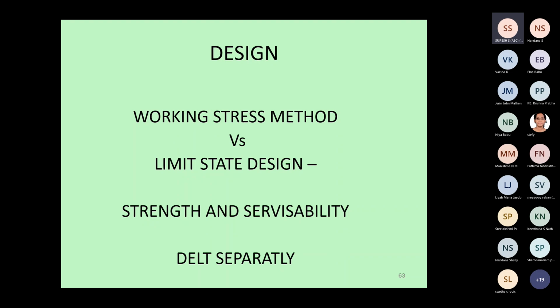It will block the wind, so the wind load will come just by building the structure in a position. If some vibrations travel on the earth, like an earthquake or a blast, the structure will generate inertia load within the structure equal to mass into acceleration, F is equal to ma, Newton's law, and thus inertial forces in the structure.